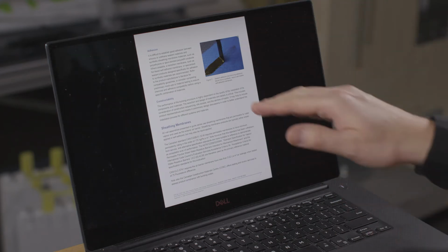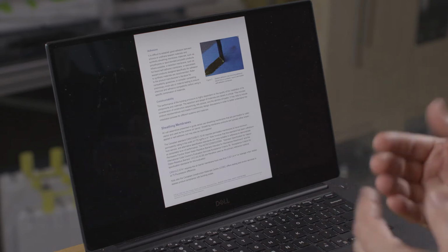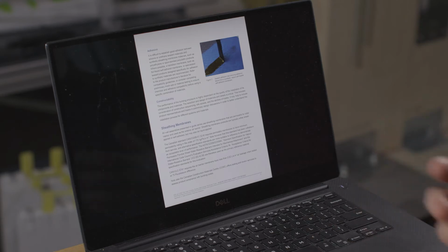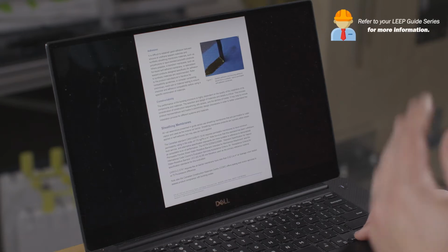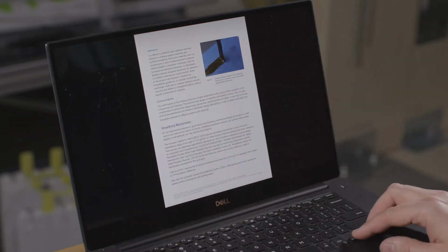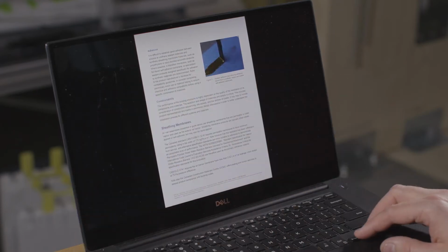Okay. Constructability. Of course, if you're using tapes and sealants and sequencing, applying in cold weather, in rain, to damp materials, all these things come into play. So the first thing we're going to look at is sheathing membranes. Sheathing membranes have a number of code requirements that are covered here, to be used as both an air and a water resistant barrier. So if you're using that sheathing membrane as the air barrier and the water resistant barrier, it needs to be tested and evaluated as such.